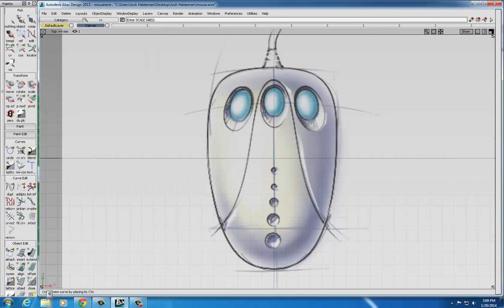And what I'm going to do to start drawing the side profile curve is go over to my Curves menu again, choose the second tool in, which is the new curves using CV, and I'm going to click and hold on that tool with my left mouse button and choose the second tool in. This is the Edit Point Curve tool. When I've got that picked, I want to pick the point in the middle of the circle at the bottom, but I need to make sure I get it exactly on that point, so I'm going to use my Snap to CV Edit Point Curve tool. And when I pick that, all I need to do is pick anywhere near this point down at the bottom. You can see it's a little red dot if you're looking at it on your screen.